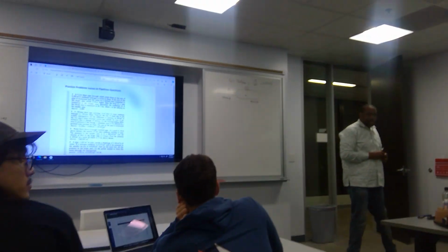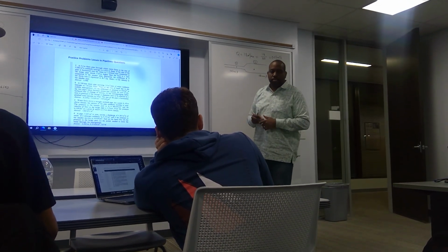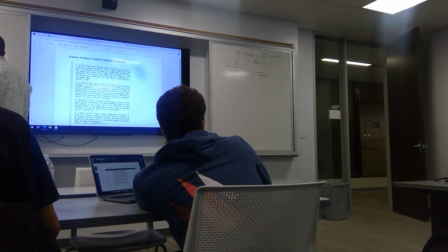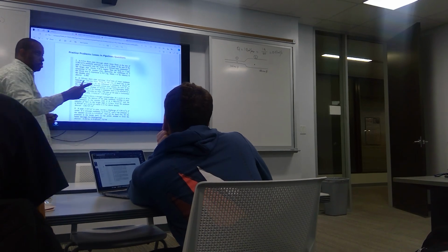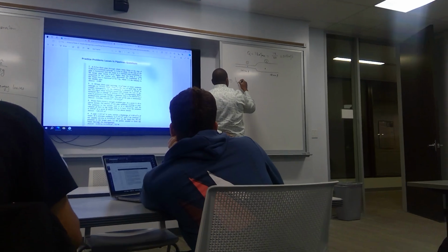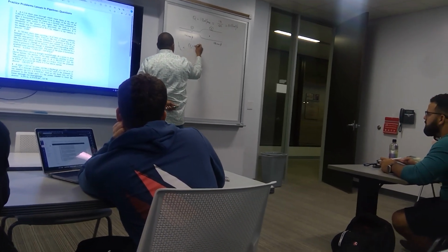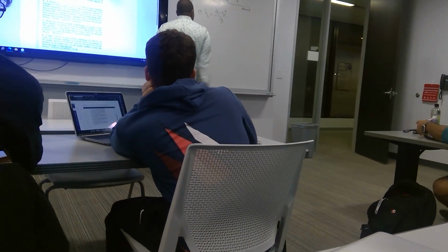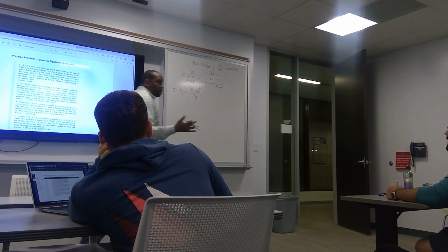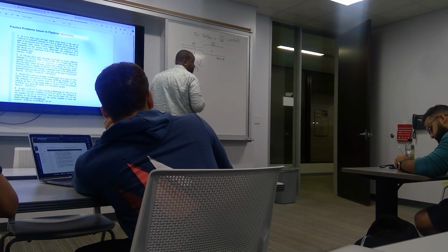How do we find that? Do we need the Bernoulli equation? No, we get it from V1 minus V2 squared, over 2g. So how are we going to find V1 and V2? The continuity equation, because we know Q and we know the diameters.